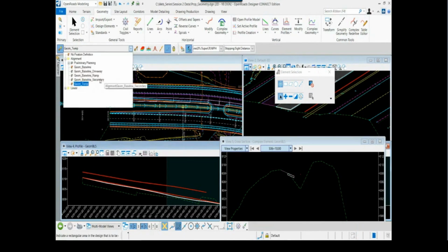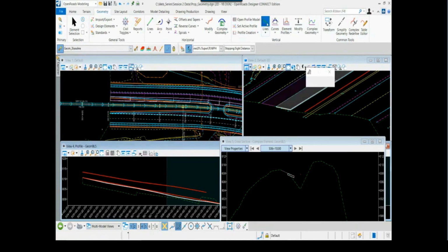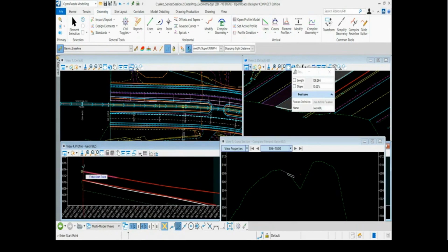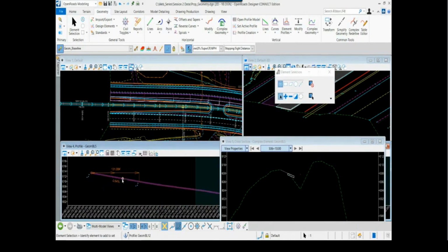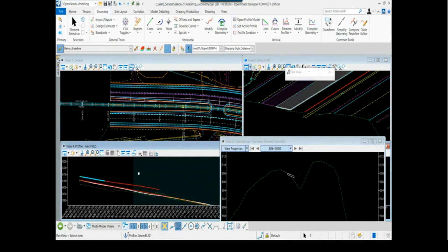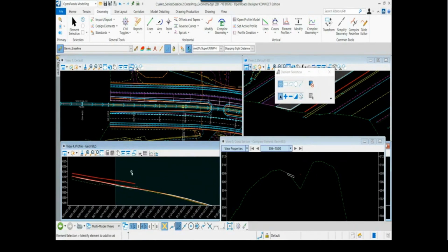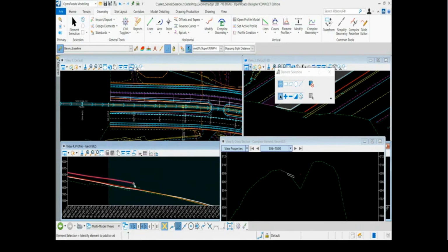We're going to create the vertical tangent first. Again, I'm going to snap here so that I'm following this. I want a smooth transition. Okay. Let's snap our vertex to there. So I now have an additional geometric element based off of that graphical display of the edge of pavement. And now I want to control the transition into that, again, common PGL area, non-bifurcated area.